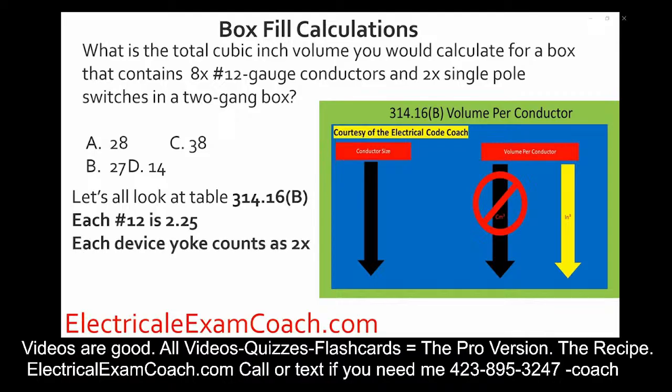Each device yoke counts as 2 based off of whatever wire is terminating to the device. We know we have 8 original conductors, and we only have one size wire, so we know it's going to get grouped with the 12s. And each one of those devices counts as 2, so we end up with 4 more number 12s, which gives us 12 12-gauge conductors. Now we take and do our math, we end up with 27 cubic inches, and we select B.